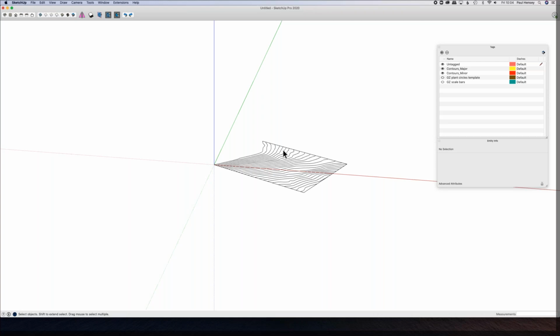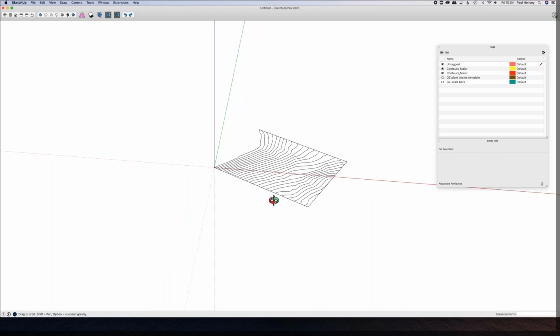It's also very nice to have a layer imported with contours in 2D, because sometimes you need to represent the terrain without seeing it in 3D. You need to lay it over a 2-dimensional drawing just to see where level changes occur relative to either existing features or proposed features. You can project 3D contours back into 2D relatively simply.